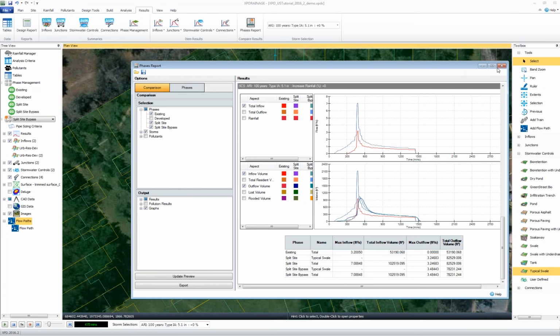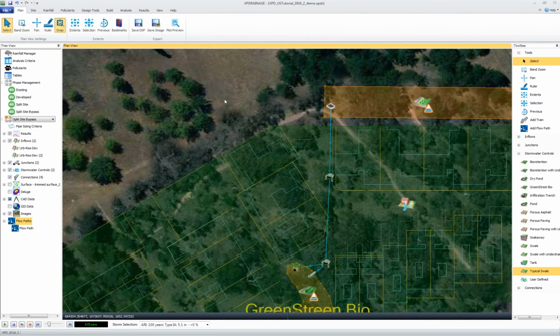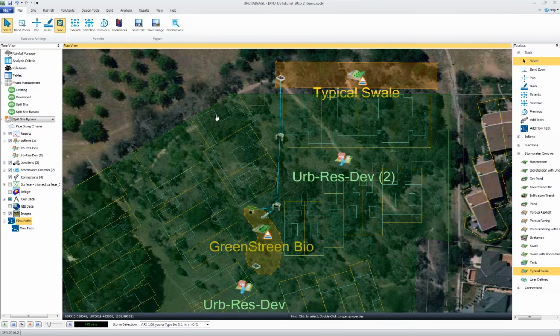There's only so much you can do to automate this design, right? We aren't going to replace engineers with an automated approach. It's just a matter of you size based on volumes, that volume water quality assessment. In a second, I'll look at the pond sizing option we have. Size that, but then you still need to run all the different types of storms and see how the combination of those rainfall events interact with your actual system and how these different facilities interact with each other. So you really do have to have some kind of look across all those different storms and go back and make a tweak.